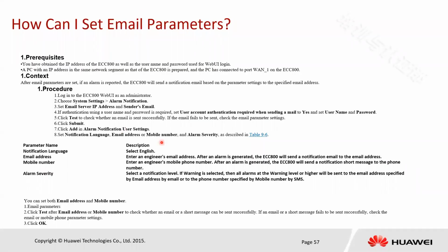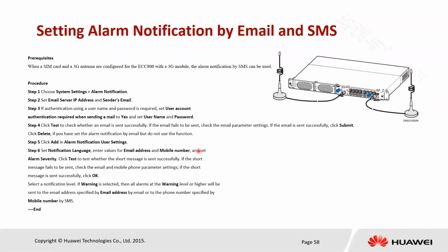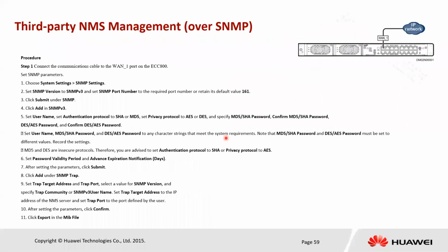So the further settings are at the configuration level. As I mentioned, this integration device can send the alarm by email. It's a very basic setting, but very convenient for getting an alarm by email. So you can configure the management people who are responsible for the data center. They can easily get the email alarm in their email box, and they can also interact with their operations team. Similarly, for SMS, if we have the SIM provision, the alarm can also be delivered by SMS. And there are SNMP settings which can further integrate it with another monitoring system, where all the data centers can talk to one central platform.